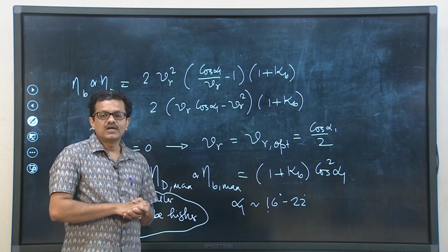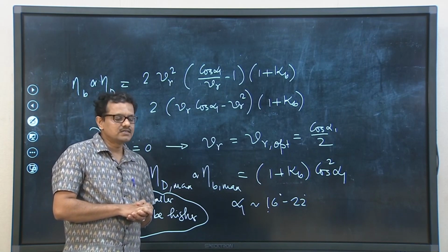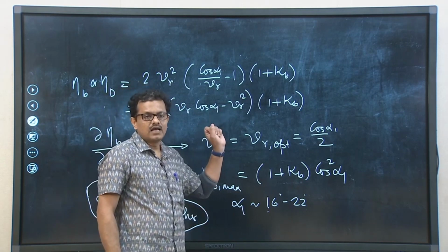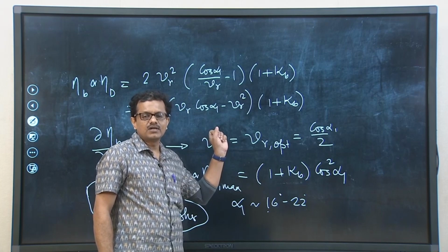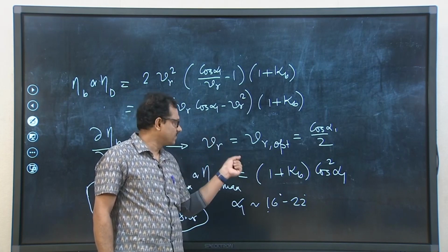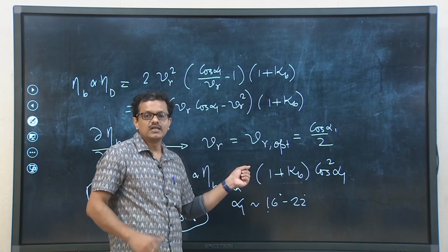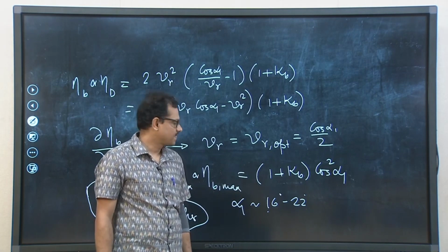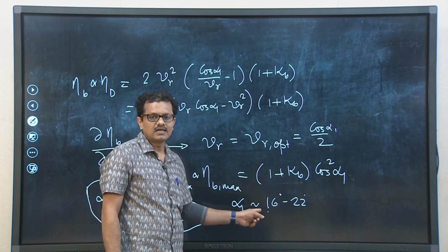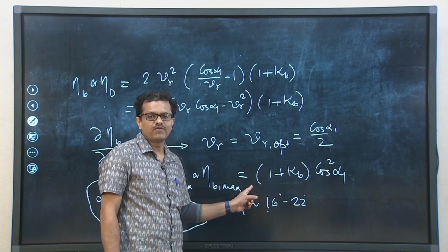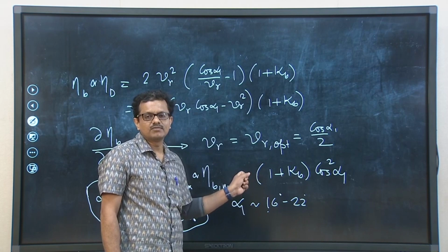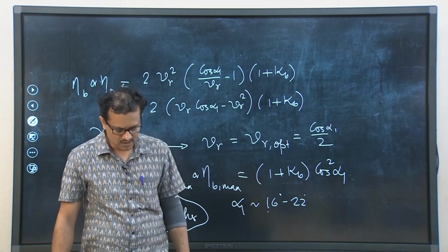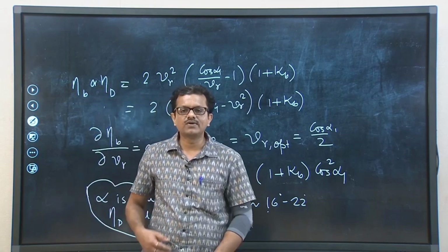We had seen that this particular efficiency is a function of several parameters, and from that expression we had established the optimum velocity ratio leading to maximum diagram or blading efficiency. Finally, we had seen the recommended value of alpha for which efficiency will be maximum without inviting extra loss of energy at the inlet of the blades. So, with this I stop here today.